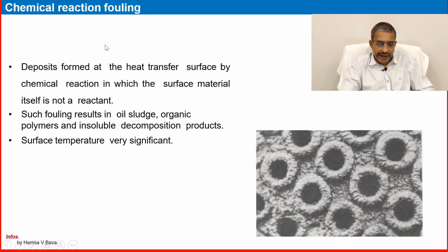So chemical reaction fouling is a reaction between the material and the fluid, either heating fluid or cooling fluid, or the contaminants. Deposit is formed at the heat transfer surface by chemical reaction in which the surface material itself is not a reactant. Such fouling results in oil sludge, organic polymer or insoluble decomposition products. Surface temperature is very significant.